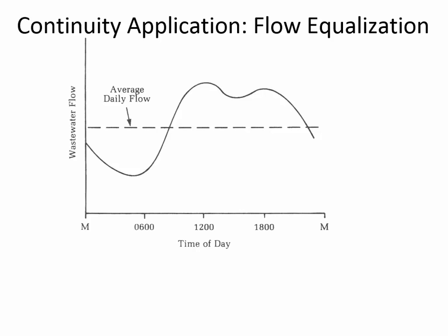Yeah, people are sleeping, don't take showers at 3 a.m. There's still a little bit of wastewater coming into the network because there are cracks in the pipe that groundwater seeps into. There are some people who maybe have set their dishwasher on a 3-hour delay, or people who work the night shift and are taking an early shower or whatever. So it never goes down to zero.